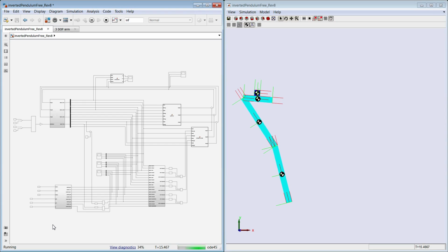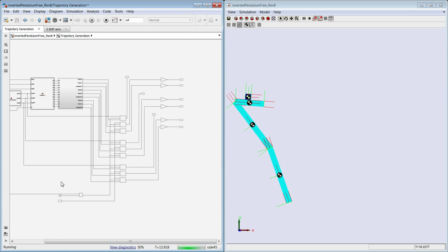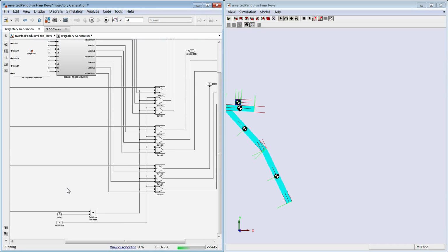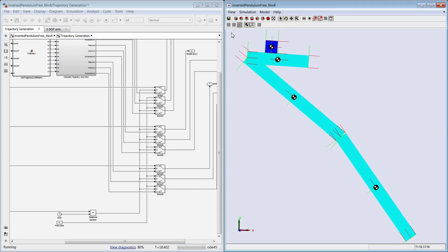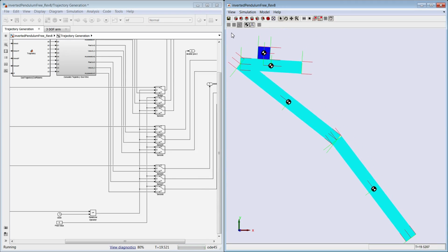One of the main concerns was trajectory generation, where once it goes beyond, since this is a high order polynomial system, the coefficient to the highest polynomial will eventually dominate the system. And since that coefficient is a negative value, it'll drive the system to a really high negative value, and you would just see this robot spinning back and forth. So that's one of the bugs.